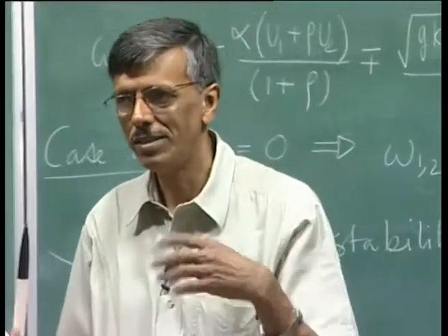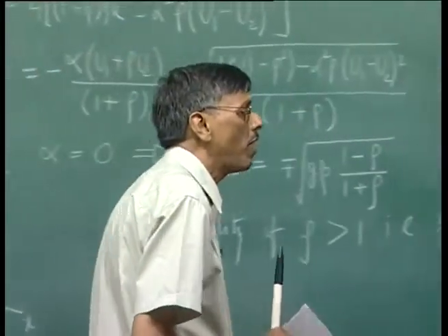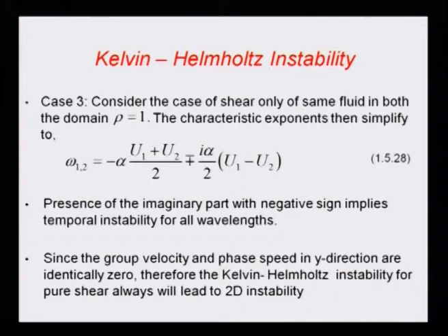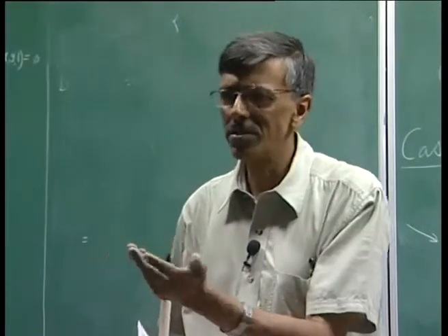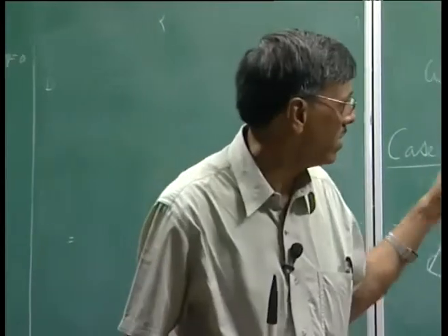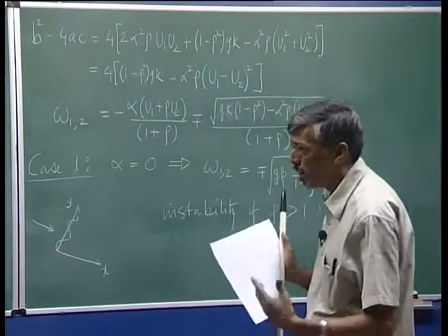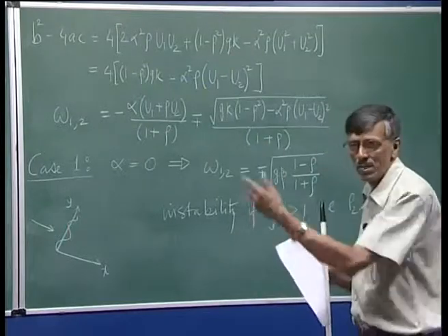If you now summarize what we have seen so far, we have considered a uniform flow above and below that interface, and that is also, we said, a very simplifying assumption, it is irrotational. And then we see that the potentially unstable temporal instabilities occur only in the direction of the flow. So, 2D disturbances are the most harmful ones, and 3D disturbances are less harmful, right, because you can see that the amplitude is given in terms of that, and the value of the shear is given by that expression that we have just now seen.